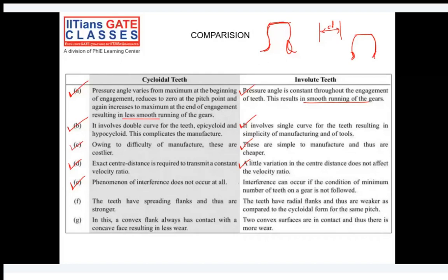What is the formula, or the criteria, for the minimum number of teeth on the gear in order to avoid interference? But as of now, you should know why interference is occurring, because of the profile difference at the bottom. Here we already have an undercut. Because the curve is concave, there is no chance of interference of the meshing gear with it.